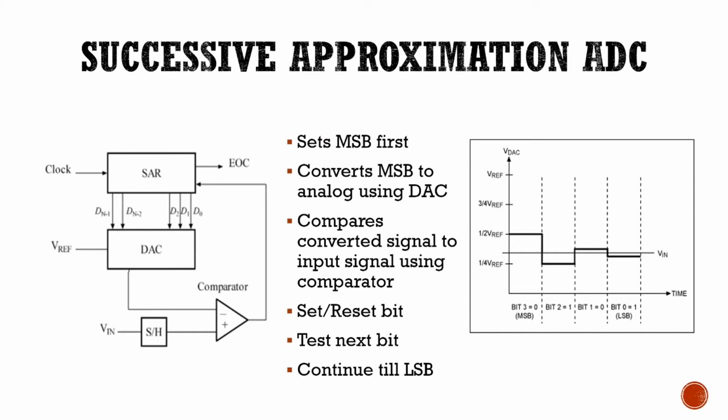The operation of a 4-bit Successive Approximation ADC can be seen in the figure on the right. You can see how initially the reference voltage was higher than the analog input voltage, and then for the next comparison the voltage was reduced, then in the next comparison it was increased by a small amount until the value became equal to the analog input signal.